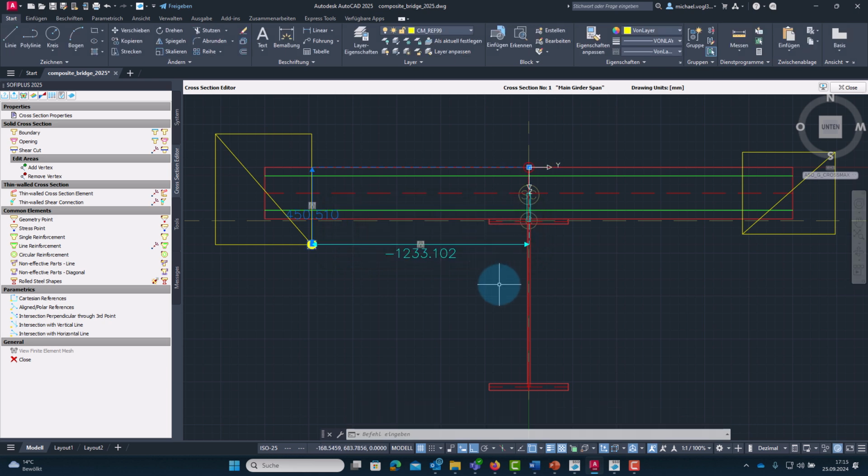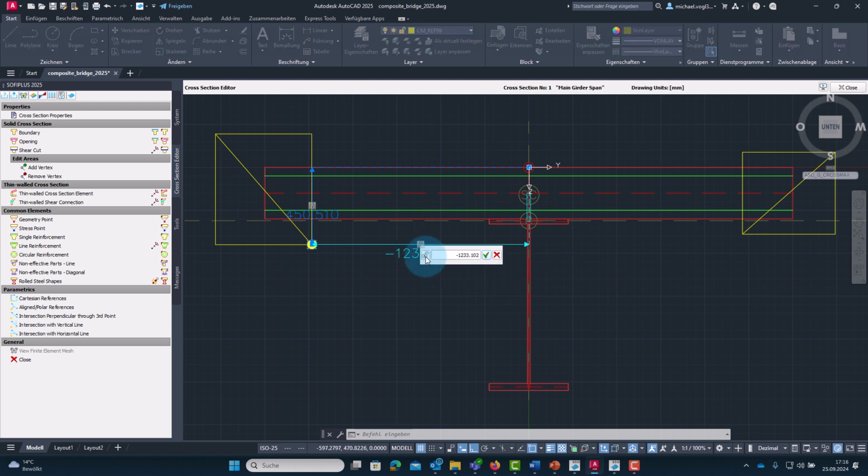To link the horizontal reference to a variable, click on it and unlock the displayed dependency. Now you can enter a new dependency. We will use the feature to enter a formula including an axis variable and assign half of the variable BF.